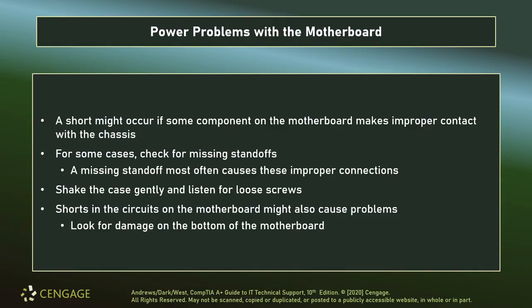Shorts in the circuits on the motherboard could also cause problems. Make sure that if there's something that happens on the underside, you're able to identify it. You may also want to check and make sure there are no loose components trapped underneath the motherboard against the chassis, which could cause a short.